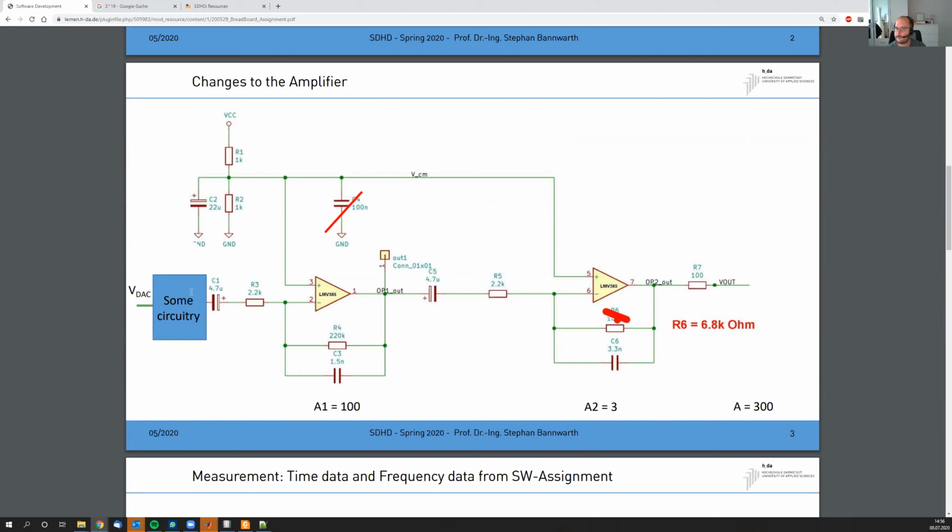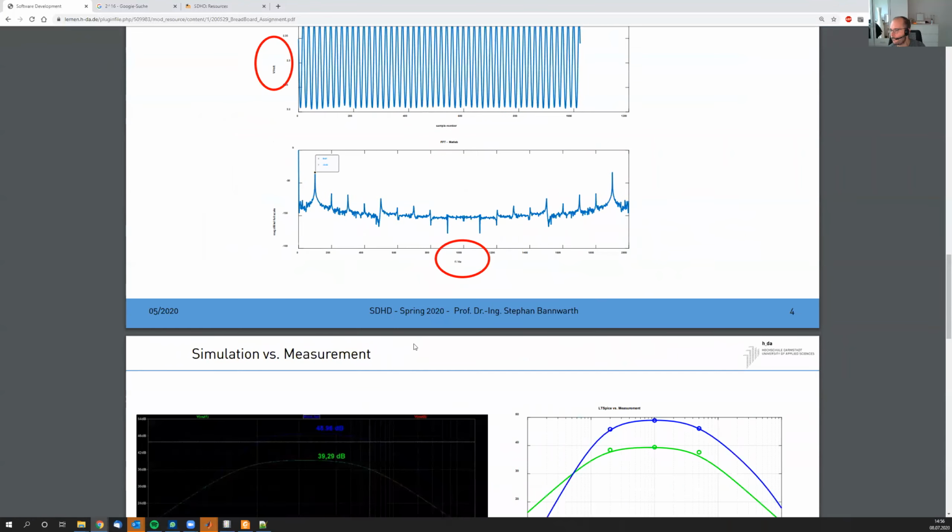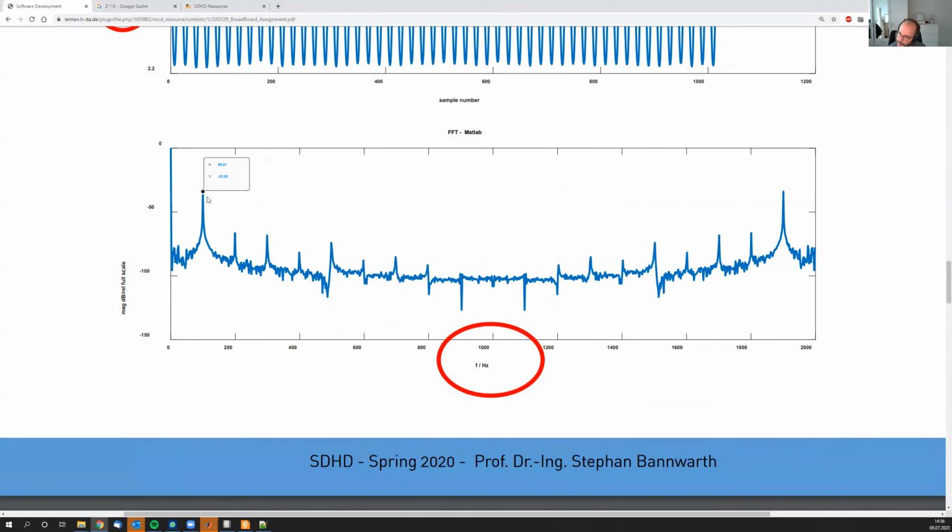Professor, I have a small question, and I'm not sure if it was addressed already, but could you please go again on how in the second graph the frequency is then, how do we obtain the frequency? Yeah. Here, this is the FFT. Basically here you see the amplitude on this axis, and here you see the frequency, and you can see that for 99.61 hertz, we have a peak here.